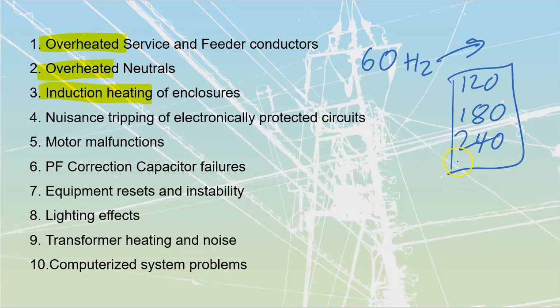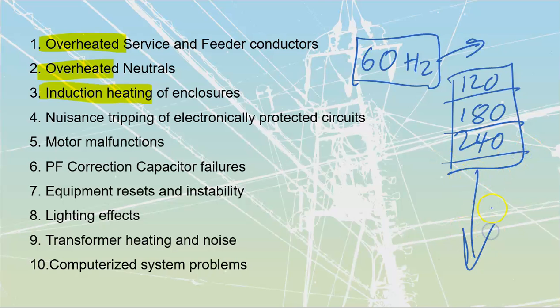And what these are is just the number of times that a sine wave goes back and forth, right? This is 60 hertz. That's what we normally have. These ones here are going back and forth twice as fast, 3 times as fast, 4 times as fast, and we go way, way further down into the system than that. As a result of that, as soon as we go into super high values of frequencies, all of our stray losses are going to go up.